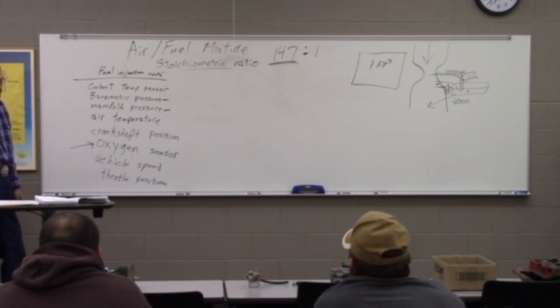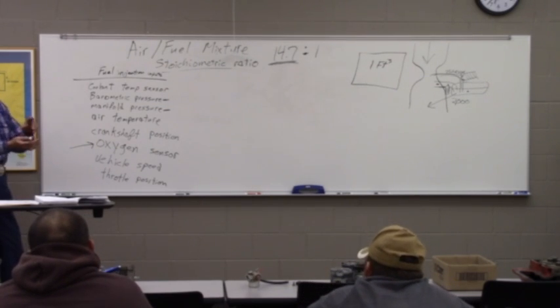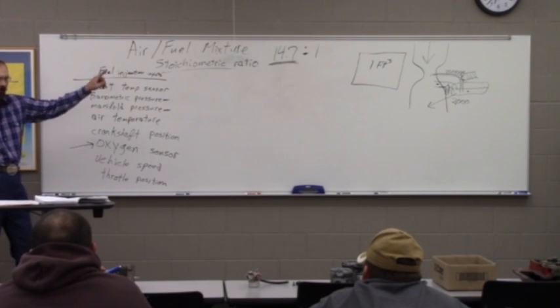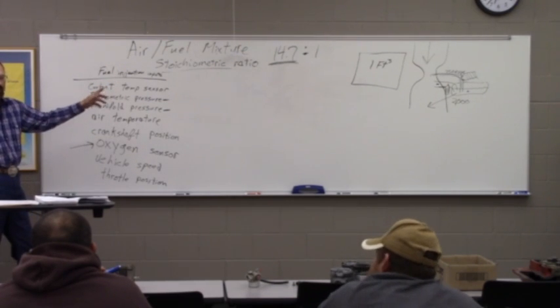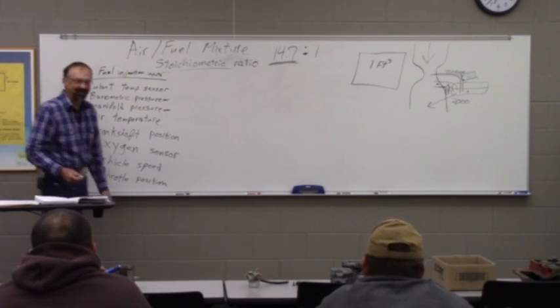But if it's working right, it should enrich it, because it knows the coolant temp is low, it knows the air temp is low, and so it's going to enrich it to help get it started, if it's working right, which is a big if, right?